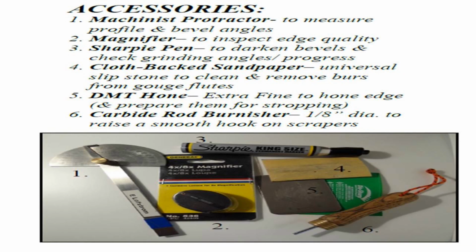Then if you have eyes like mine, a magnifying glass is good, where you can actually see the surface. A Sharpie pen is great. When you first start and you're going to resharpen, you take a Sharpie and cover the surface that you're going to resharpen, and just a quick pass will tell you, do you have it set up correctly? Does that stone cut the entire surface, or the bottom half, or the top half, so you can make adjustments before you get started with it.